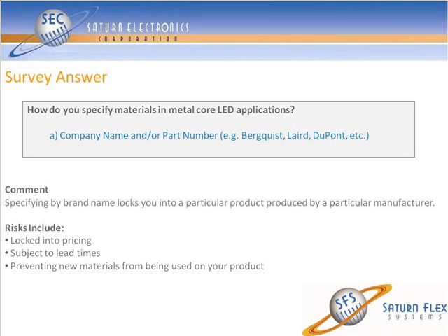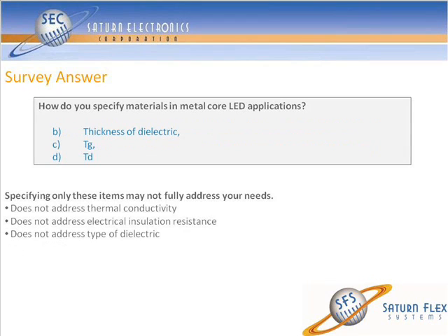Thickness of dielectric, TG, TD: these are all good things to call out. They may have an impact on reliability, but they don't fully address your needs, which are actually moving heat from your component. So again, you're not addressing thermal conductivity, you're not addressing electrical insulation resistance, and you're not addressing the actual type of dielectric that you're looking for.